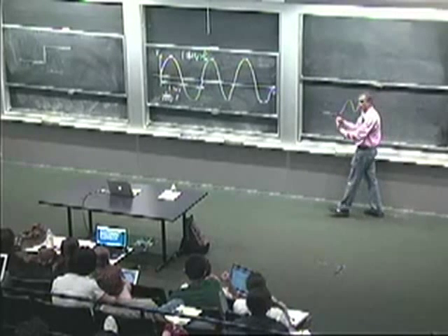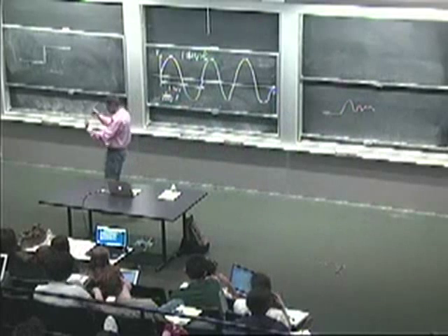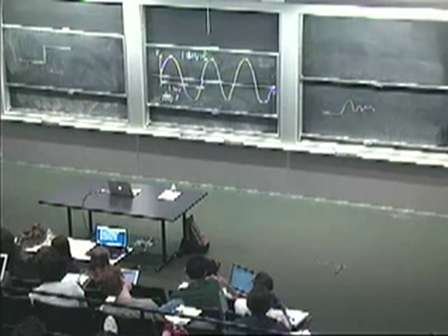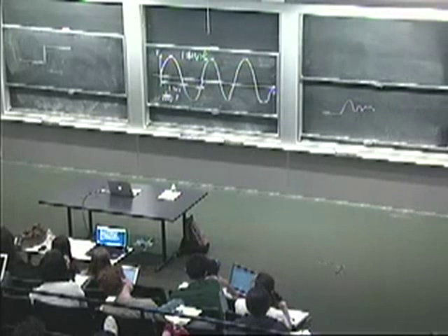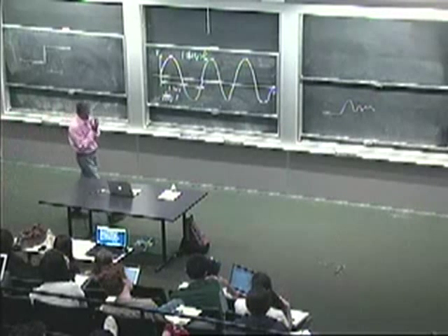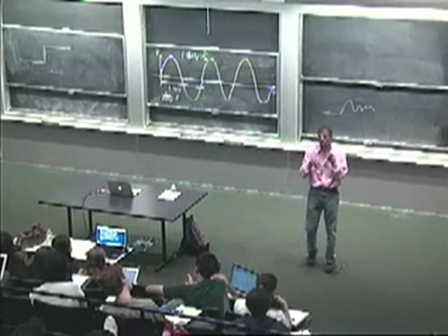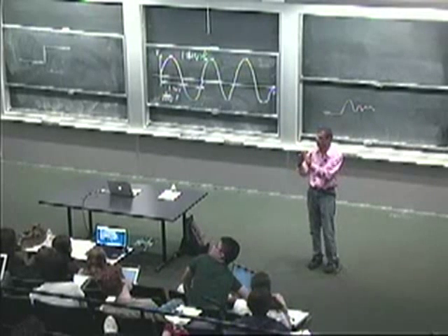What I'm going to end up with is this combination of zeros and ones that are sort of random, confusing the receiver, because we're not giving enough time for the 0 to settle down, and similarly, when we go from a 0 to a 1, we're not giving enough time for the 1 to settle down. That's what this eye diagram was referring to, where we found in this confused case, and then when you have noise, some of the zeros get moved to a 1 anyway, and ones get moved to a 0, and we end up with this very crowded picture.